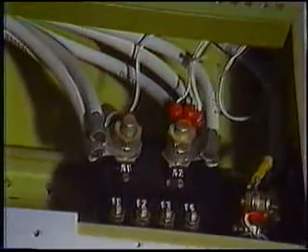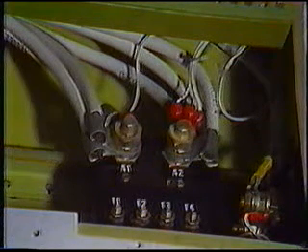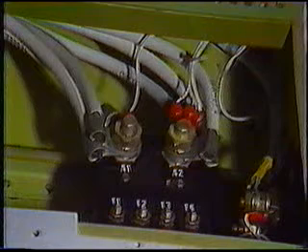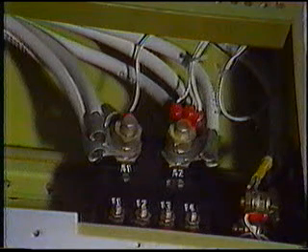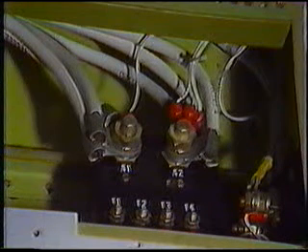Several relays are used in the generator system. The largest of these is the generator relay itself, referred to as the main contactor. It is installed in the right-hand side of each nacelle. This is the primary means of connecting and disconnecting the generator to the aircraft wiring system.